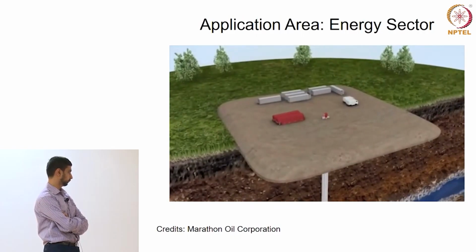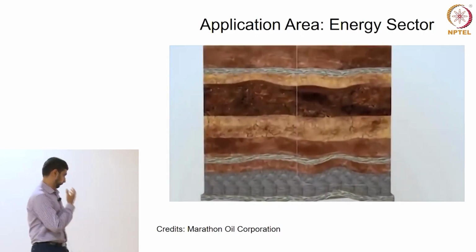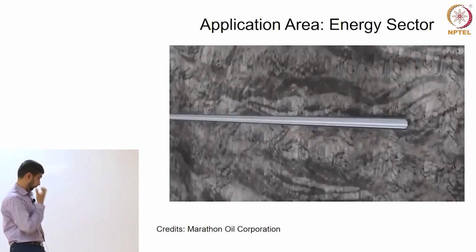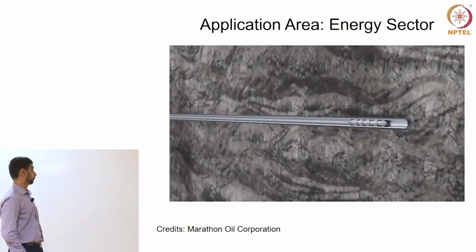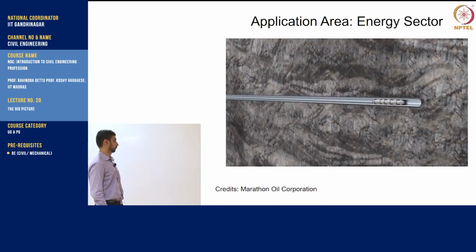Well completion. The first step in completing a well is the creation of a connection between the final casing and the reservoir rock. This consists of lowering a specialized tool called a perforating gun, which is equipped with shaped explosive charges, down to the rock layer containing oil or natural gas. This perforating gun is then fired, which creates holes through the casing, cement, and into the target rock. These perforating holes connect the reservoir and the wellbore.